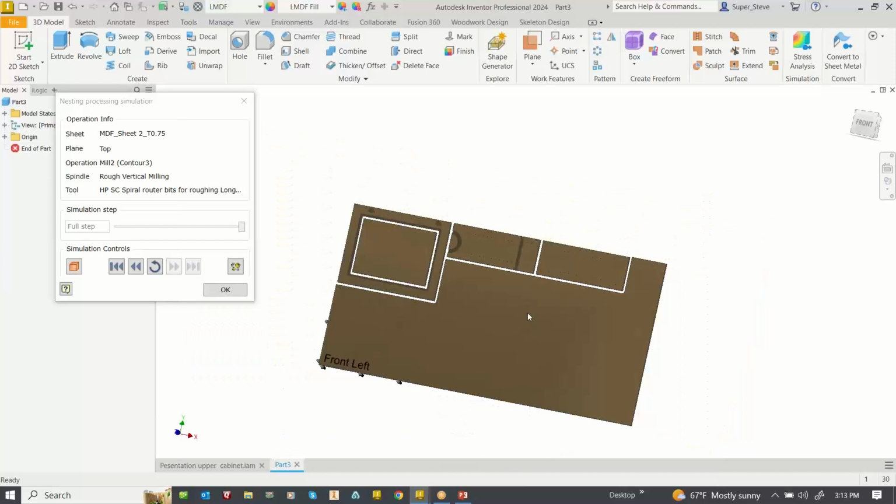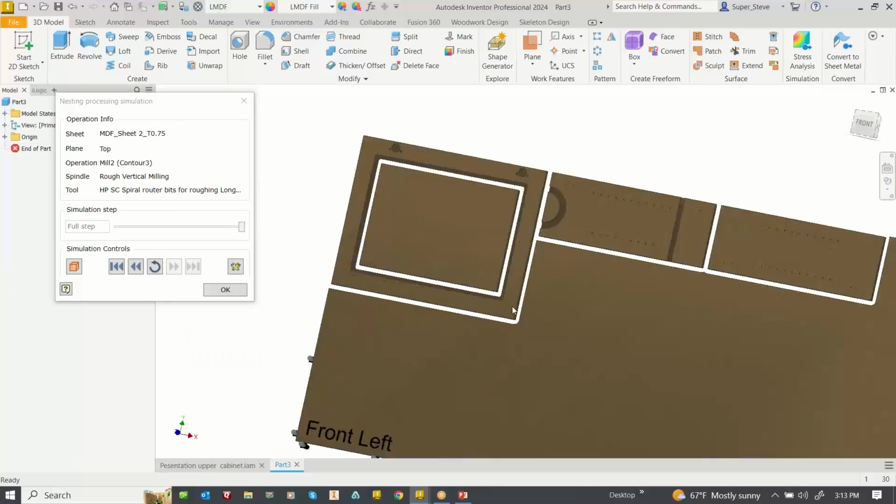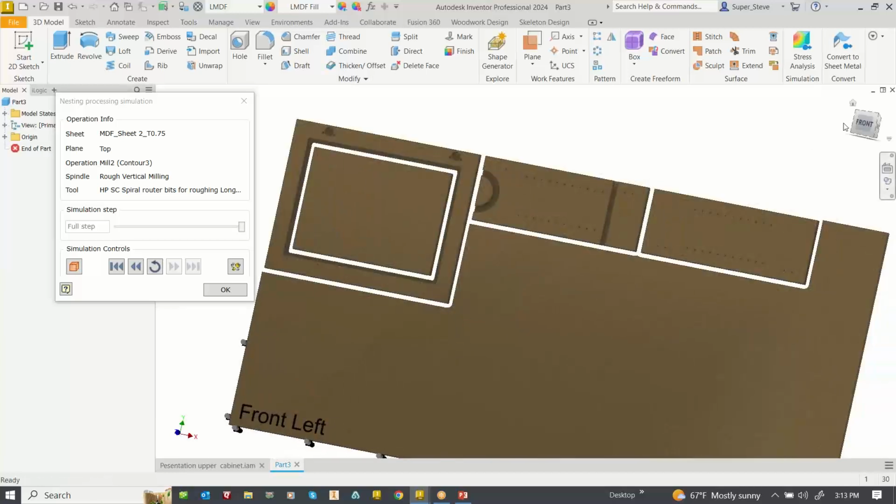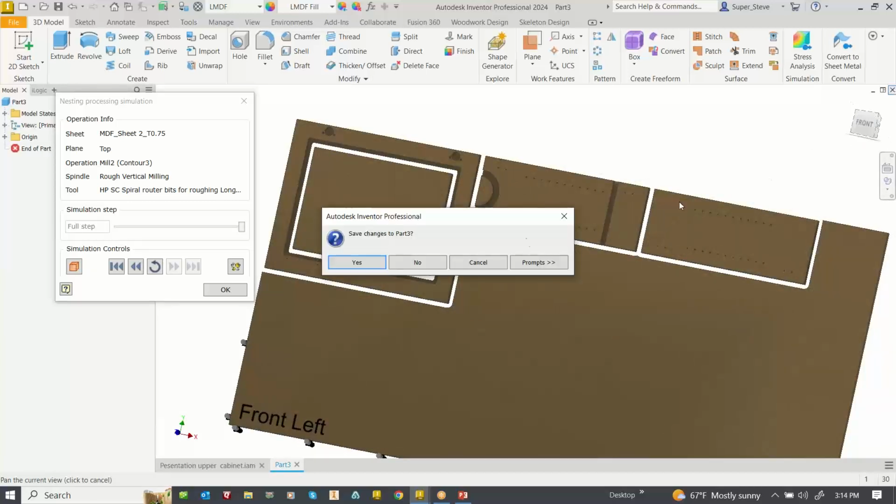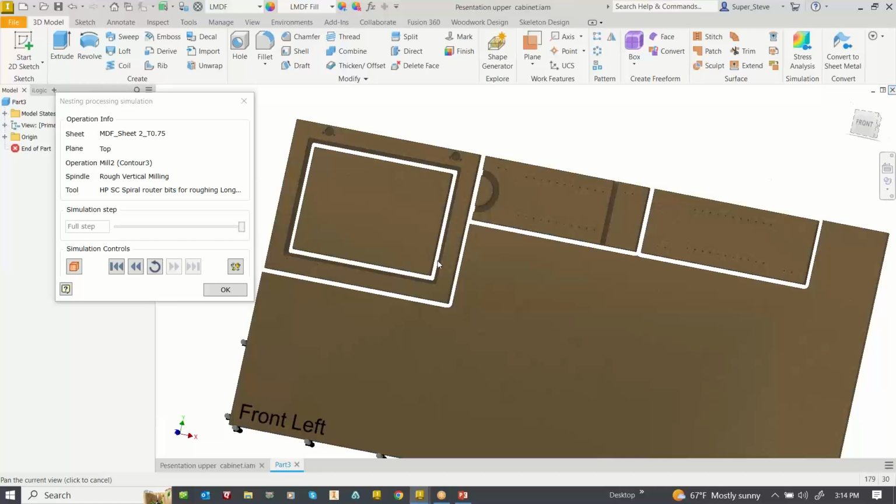So that's done. The spacing between the parts are fully adjustable. You can have single line cut where the tool does a single pass and machines both sides. It's a little rough. You know, usually most machines don't do the best job. They get some tear outs. But if you want, you can do a double cut or a triple cut. Again, all of that is adjustable based on the equipment that you have. So it's very, very variable.